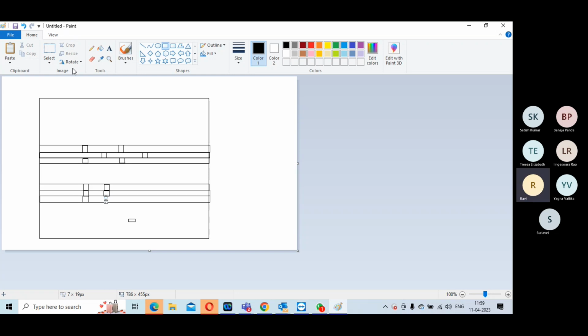When you add decaps, it helps you improve your dynamic IR. But at the same time, it adds leakage current to your design, and it adds substrate capacitance too. So power consumption is an important problem, but decaps are good, so you have to add them in the right quantity. 1 in every 4 cells is a good decap combination.